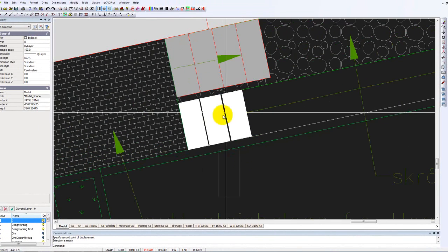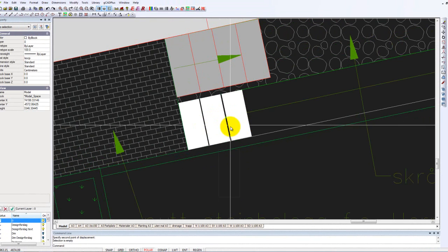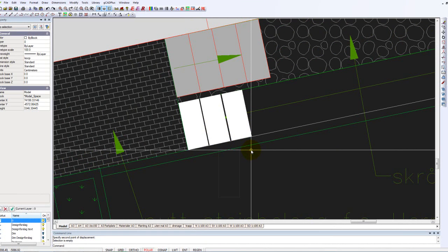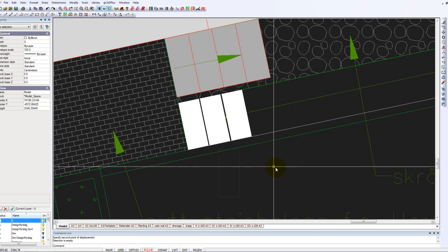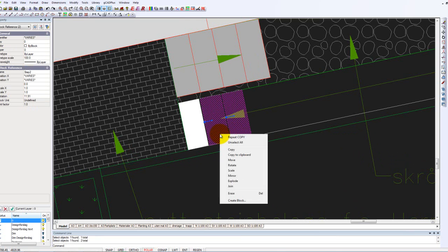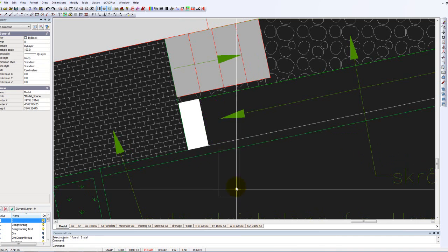Now I've deliberately left a gap there. What we could do is pick a distance step setting of something like 350 plus whatever gap you want to leave, or set it at 350 and they'll butt onto one another. So let's pick those lines which we placed arbitrarily as far as distance apart, but accurately as far as the angle was concerned. Let's erase those.